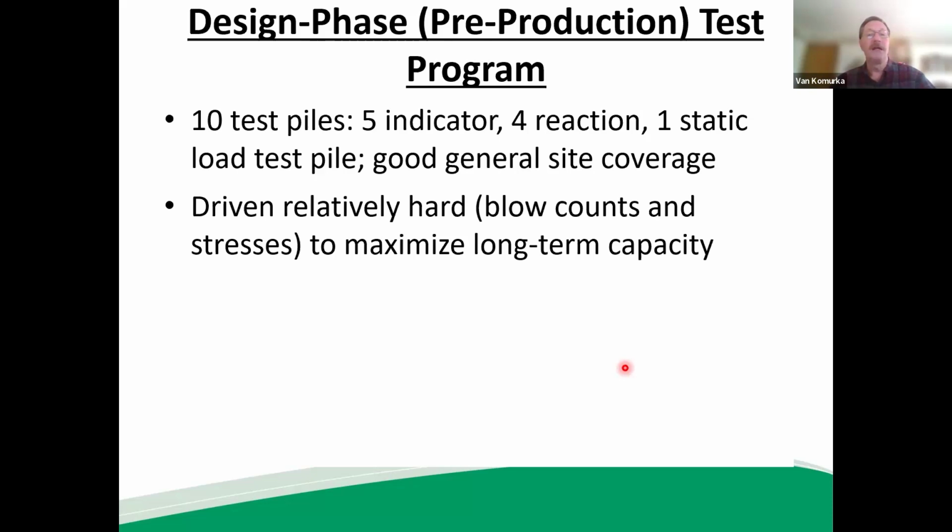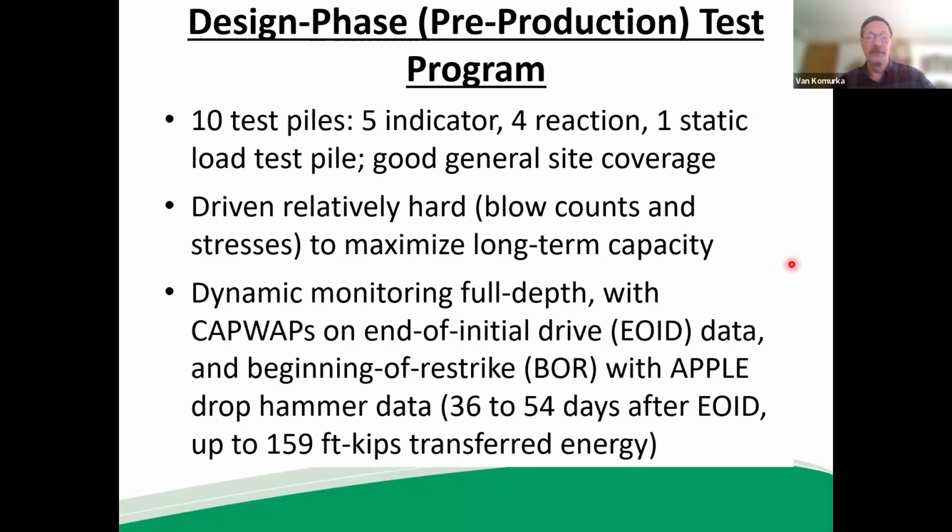The most economy in any driven pile installation is to drive a pile to near its driven stress limit, and then have that driven stress limit be near practical refusal blow count. That's the best way to install a pile in terms of economics. And then also to load it geotechnically to near its structural capacity. Those 3 things add up to the most economical pile installation.